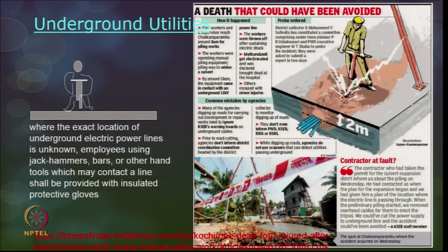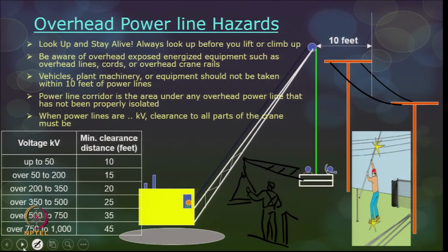injury. So, you should have a proper insulated device, even for crowbars or something, so that it is not coming in touch with your body, and also you should have proper insulated protective gloves and other precautions and proper PPE when you are working on underground utilities, okay, especially when you couldn't even track where the underground utilities are lying below the soil level. So, this is an article which has been taken up showing electrocution.